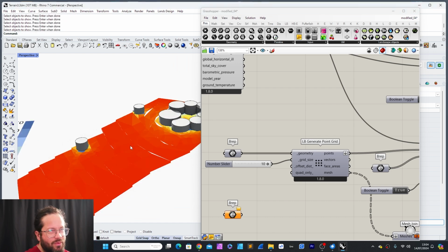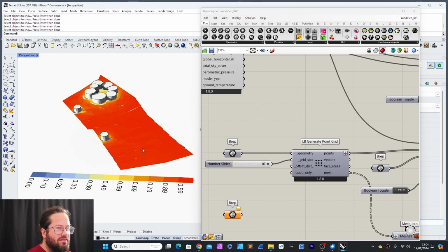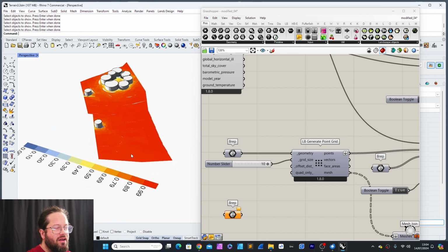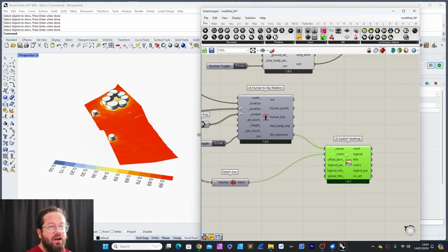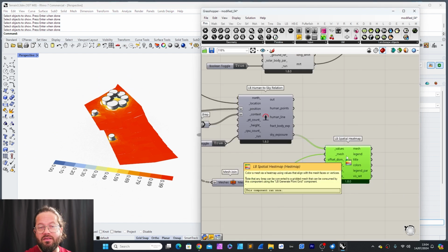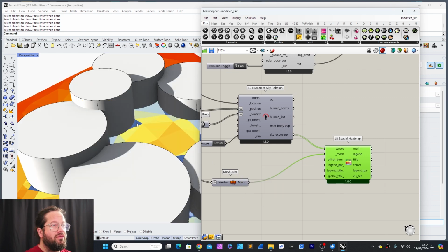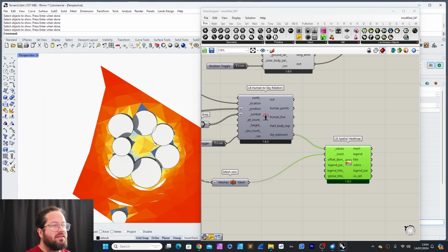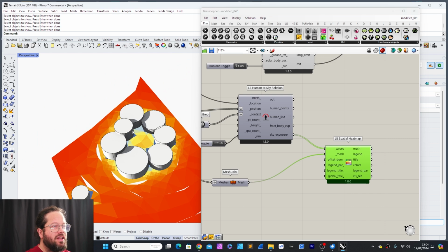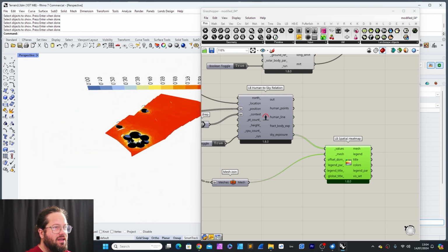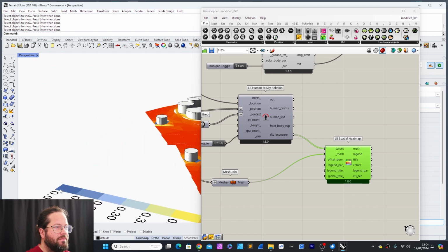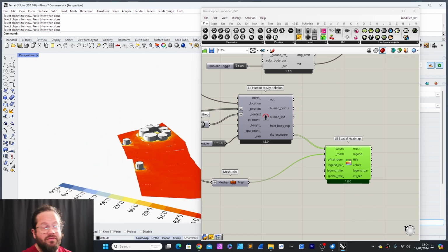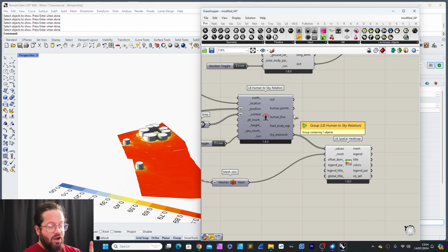It's pretty red everywhere. What does that now mean? So what it means is that we have 0.99 as a factor for this human to sky relationship. So we calculated how likely is it that you are exposed to the sky. And within here, you see there's a bit less. You're not 100% exposed to the sky in some areas. Like when you're inside, then it's completely blue. That means it's 0%, or 0 as a factor. All right, that has nothing to do with the outdoor comfort yet.